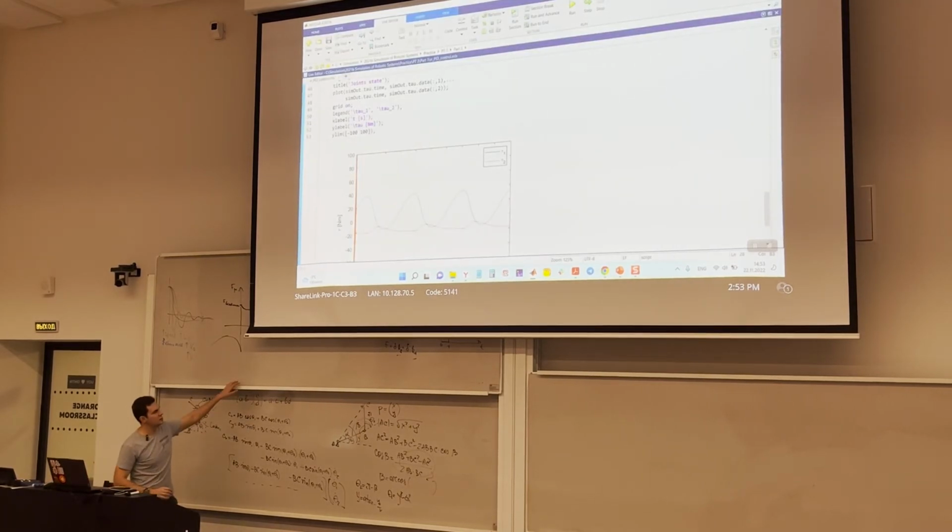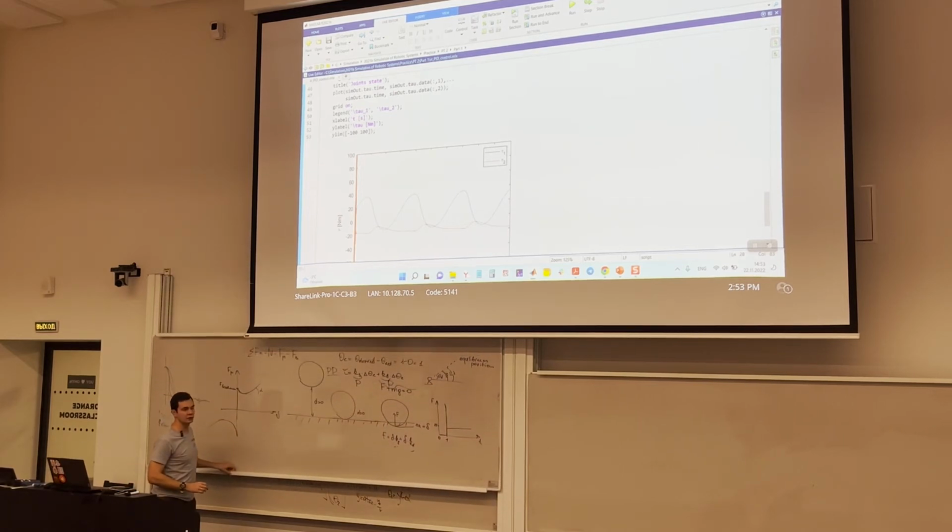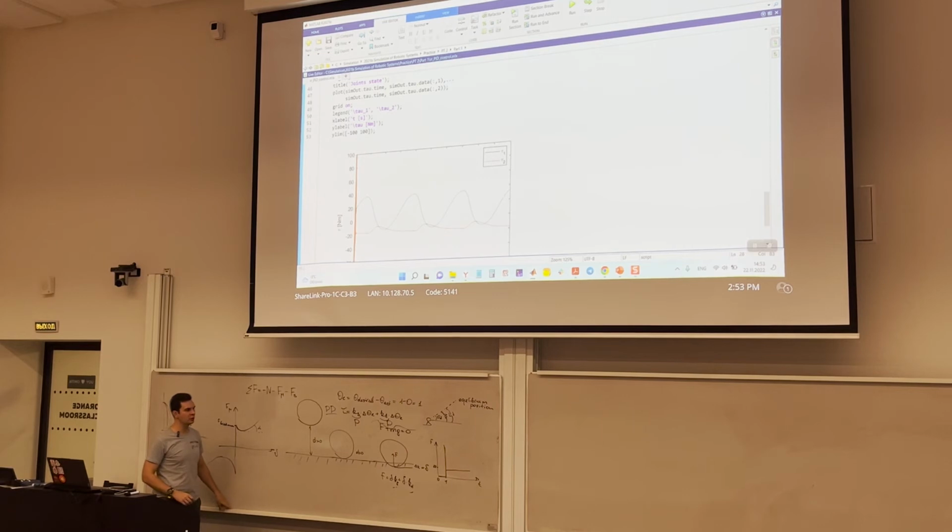By the way, speaking of contact, what do you think will happen if we're going to use PID control without saturation to interact with the environment? By the way, according to our rule, we can use position control only and only if the robot is isolated. Do you remember this? But why is that? Let us suppose that we use PID control to implement position control, and your robot is interacting with the environment, and we use this kind of contact modeling. What will happen?